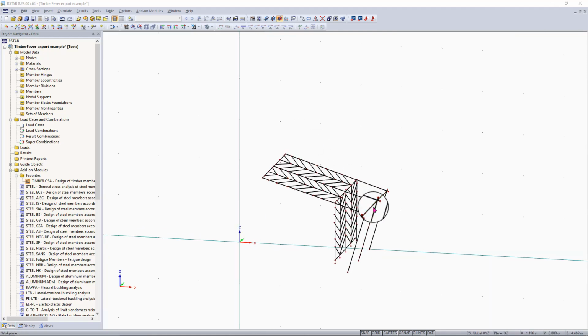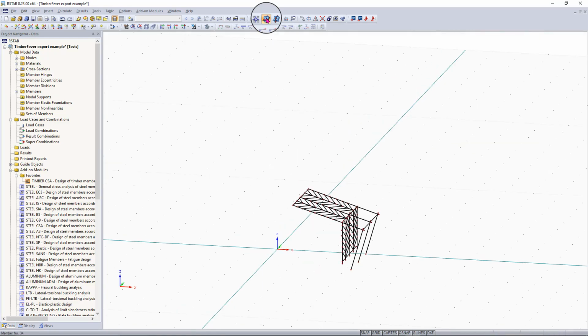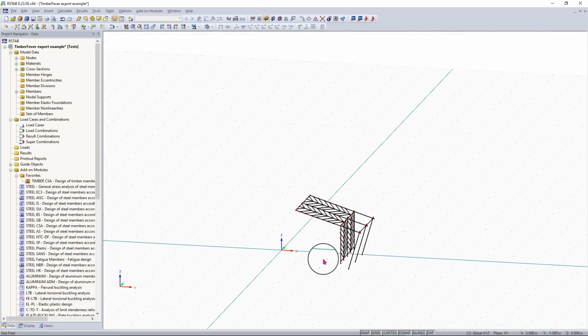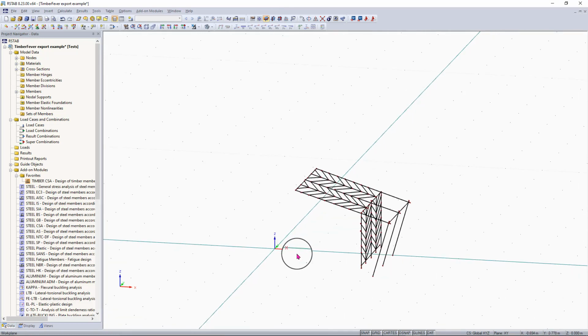What we can do is first change this work plane up here with these buttons, and we can click on this one called work plane in the XY. So I'll click that, and then you'll see that this grid with the grid points and everything is switched to the XY plane. And you'll also see that these grid points are spaced out evenly.